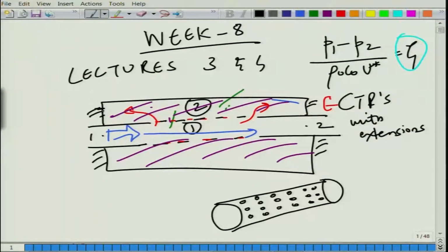So, here one needs to go to structural acoustics concepts. Here at this interface, the normal velocity of the fluid is equal to the time rate of displacement normal to the plane of the plate, and your plate itself is governed by maybe your Kirchhoff equation. It could be a thin or thick circular plate with a concentric hole at the middle, and then your other condition is a pressure condition which acts like a loading condition, and this will radiate noise outside in the far field, and similarly here.